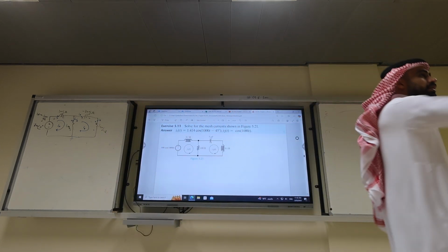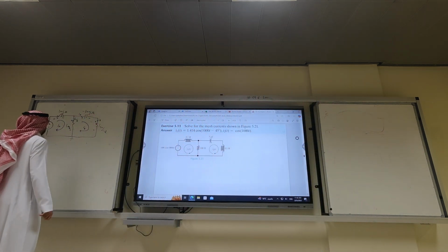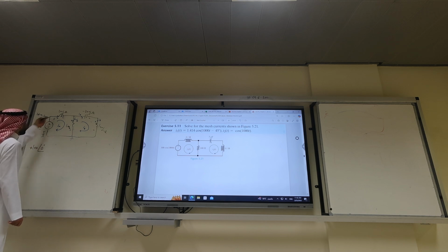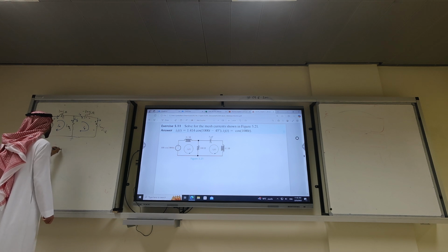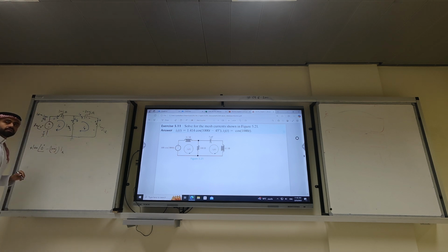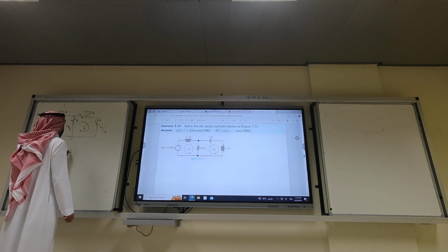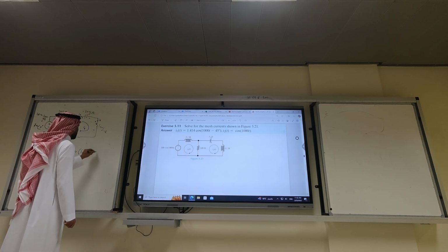Any problem? No. Okay. Who wants to be the KVL? Justin. This is Justin. Start. Voltage rise, voltage drop. Voltage rise with the sign. 100 angle 0 plus 100 angle 0. And then voltage drop minus 100j times IA. Right. And then voltage rise, voltage drop. Minus 100 times IA minus IB equal 0.